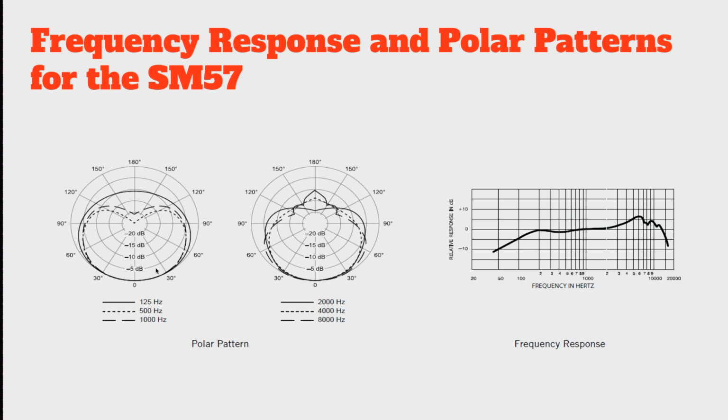At other frequencies, it kind of comes off not quite cardioid-like. We don't really have a null on the rear here at this very low frequency point, which I believe in the legend is maybe 125 hertz. We actually get kind of a squished omnidirectional response.